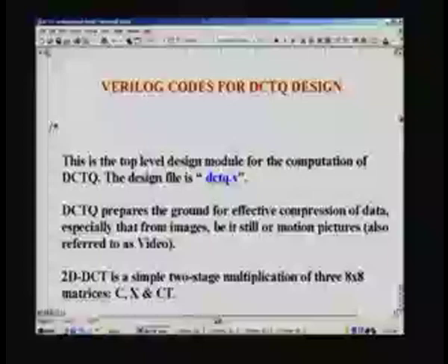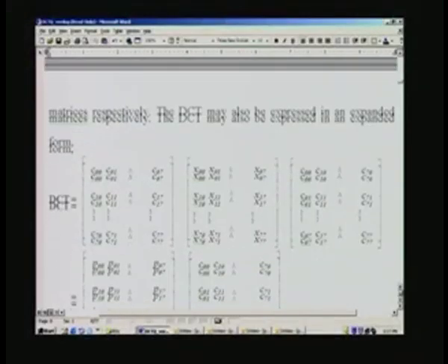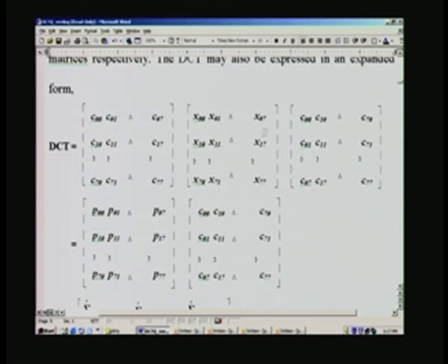basic thing behind this is, see, for example, this is the realization of DCT, which has 3 matrices of 8 by 8, and we have seen that the computation load is very high. As in your question, suppose we have used 16 by 16, what will happen? Each of them will be a huge matrix. Just imagine multiplying, how many multipliers you require? What will be the chip area? It will increase exponentially, so it will soon become impractical. Had you used 16 by 16 instead of 8 by 8, the chip area would be too impracticable.